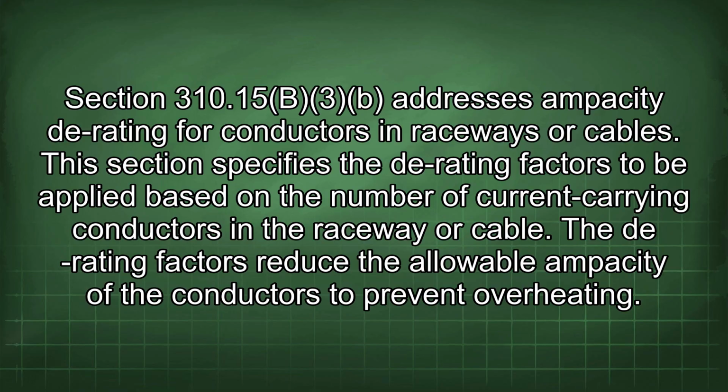This section specifies the derating factors to be applied based on the number of current carrying conductors in the raceway or cable. The derating factors reduce the allowable ampacity of the conductors to prevent overheating.